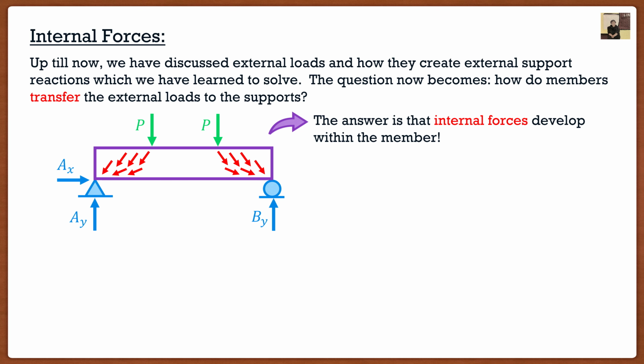Now, why is this going to be an important topic? Well, as we're going to see, these internal forces actually govern our design. There's going to be 3 internal forces, and each one is going to play a very critical role. Now, as a structural engineer, this is my whole goal. What I do is I analyze the loads on a beam, and I determine their internal forces. And then I pick an adequate beam to resist each of these internal forces. Again, that's my whole goal as a structural engineer. If you do that, your building is mostly safe. There's other considerations we have to consider, but the main goal of structural engineering is to pick beams or columns or whatever you want to resist these internal forces. So they're actually very critical in design.